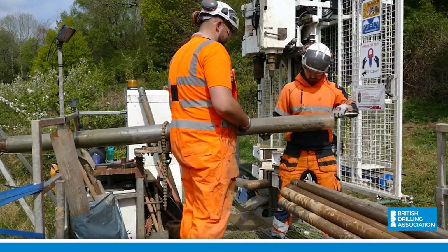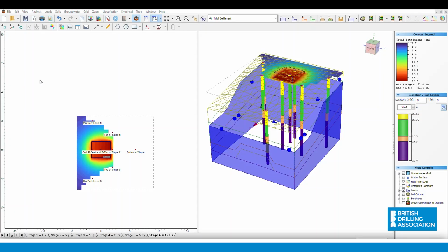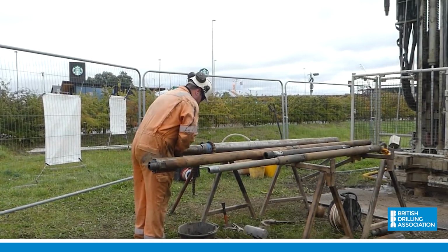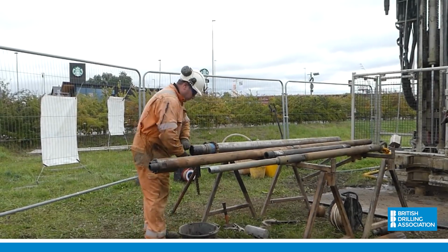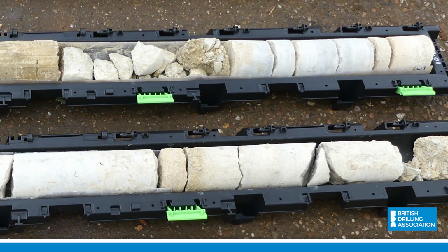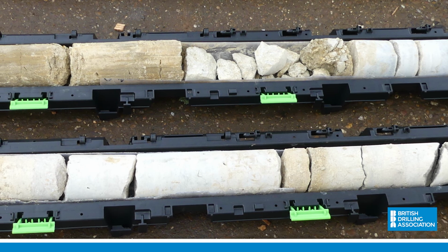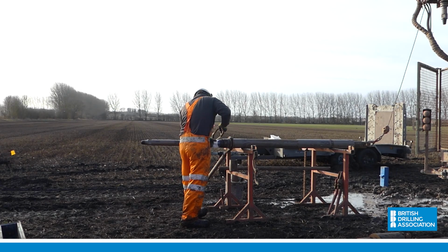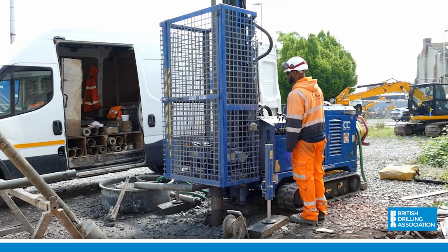The driller provides the sample, the lab tests it, the engineers develop their solutions around the results. However, each step is reliant on the original sampling being done correctly and with due care and attention. Crucially, it is the quality of the sample that determines what laboratory tests can be carried out and how reliable the subsequent data and defined characteristics for design purposes are.